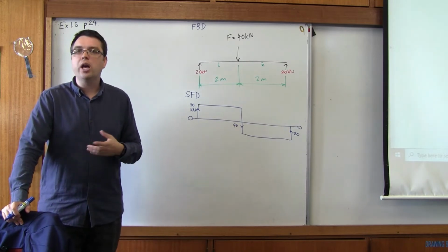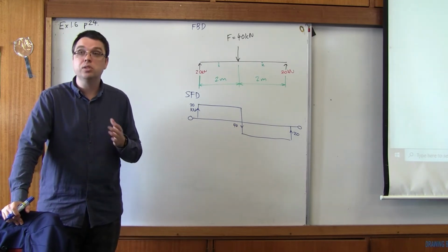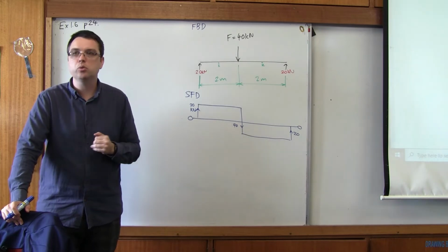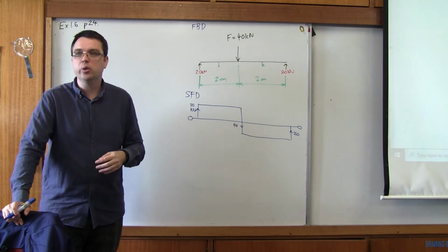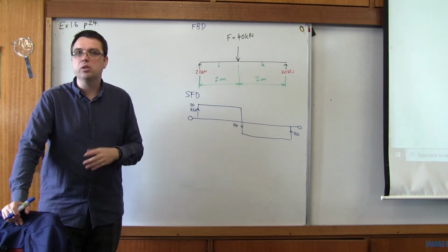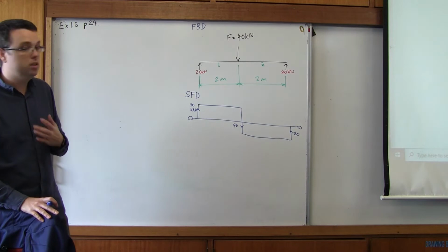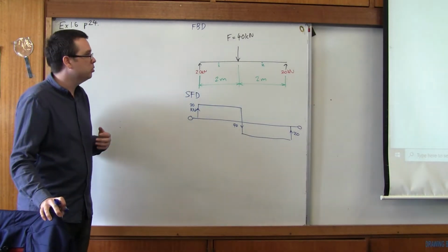Right? So how do we do that? For concrete, we use stirrups. Right, we use vertical reinforcement called stirrups. For steel, you just do a quick check to say, yep, it's fine. Because with steel, shear is very rarely a problem, at least in my professional experience.